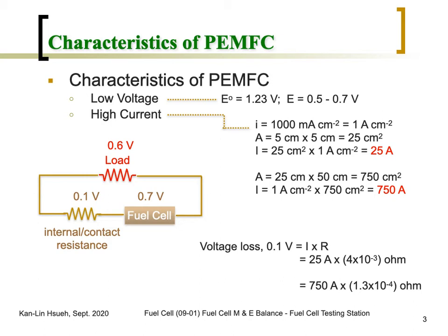If there is any rust or some problem with the contact area, you will create a huge resistance, and then you need a very thick cable to reduce any contact resistance. So with this kind of current, the alligator clip, those kinds of things cannot be used.